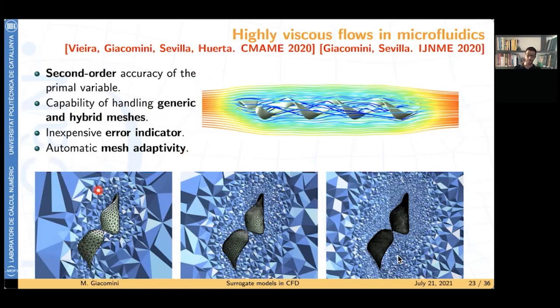And here I'm representing the 3 levels of mesh refinement near the head of the microswimmer here. In this region, of course, the flow is extremely complicated, specifically due to the complex geometry of the neck of the microswimmer. So we were able to devise a method which is completely insensitive to mesh quality and perform simulation using finite volume in this context.